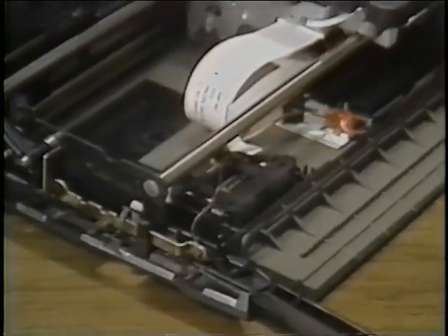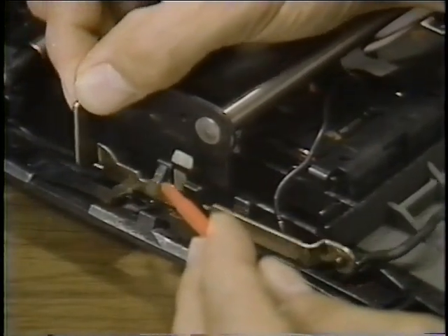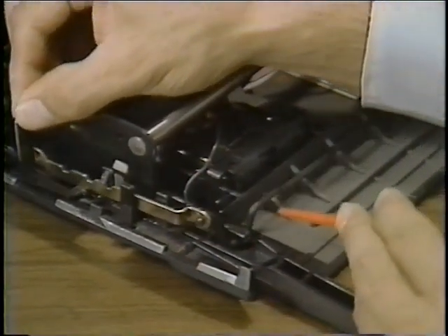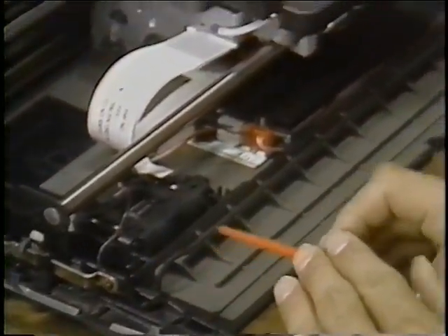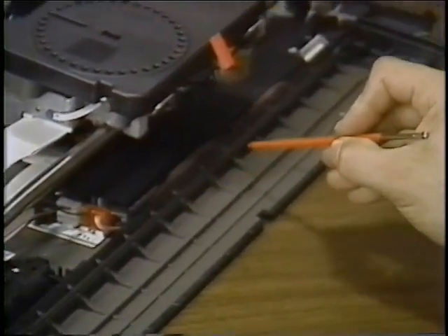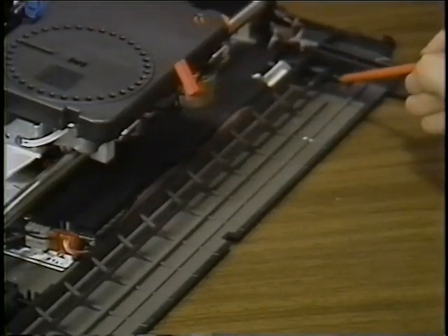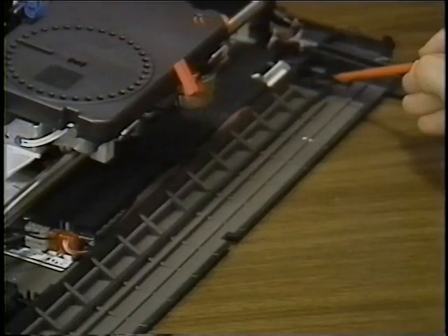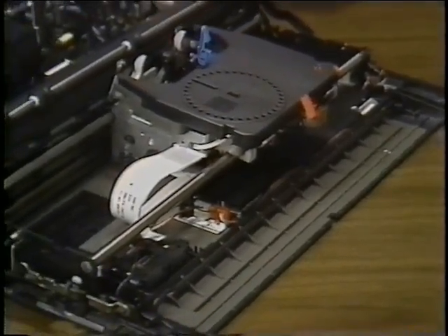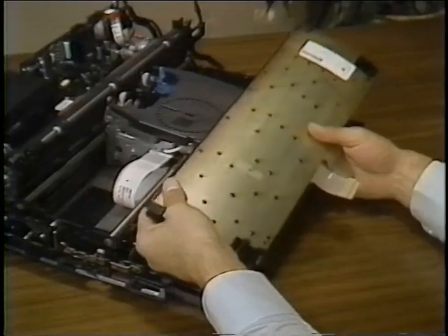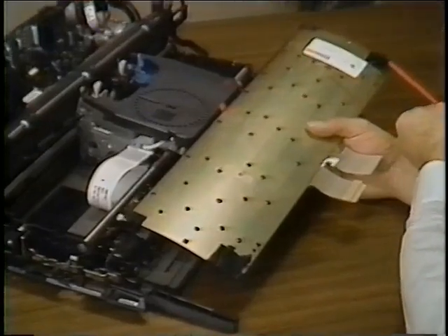Before we put the keyboard back in, let's take a look at how the keyboard adjusting lever works. The lever has 3 detent positions. This is the keyboard adjusting bail. As the keyboard adjust lever moves to the rear, the adjusting bail rotates to the rear. Notice that there is a high point at each end of the bail. The high points on the keyboard adjusting bail fit into these camming surfaces on the keyboard mounting brackets.